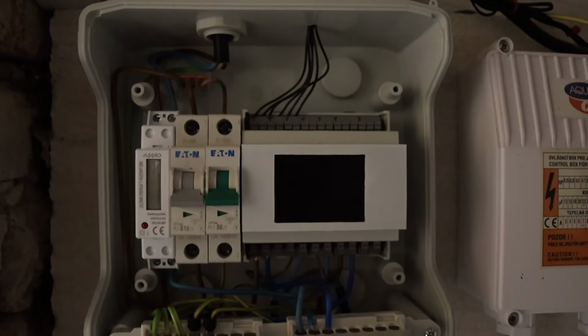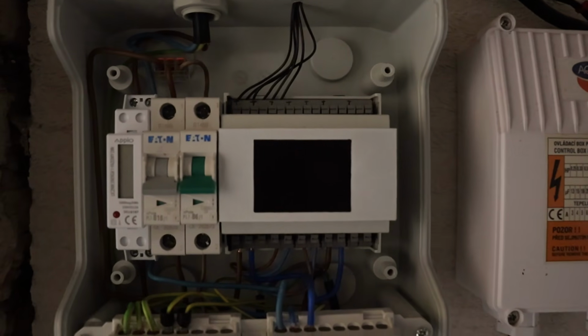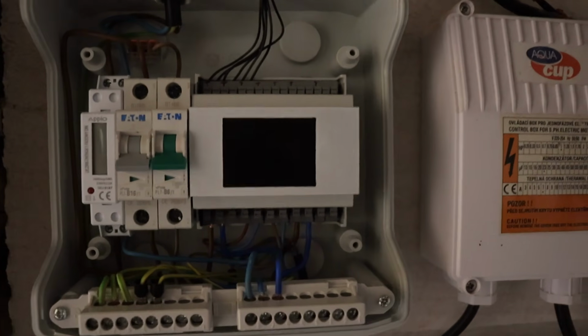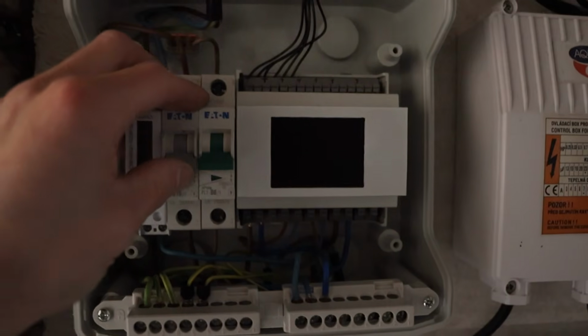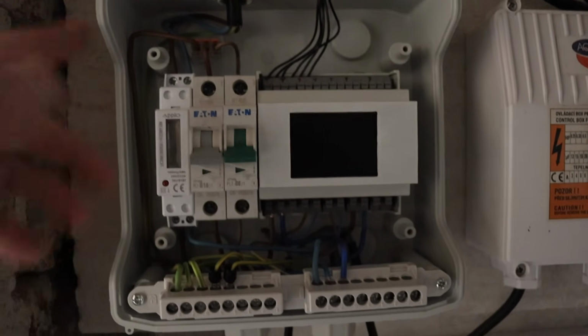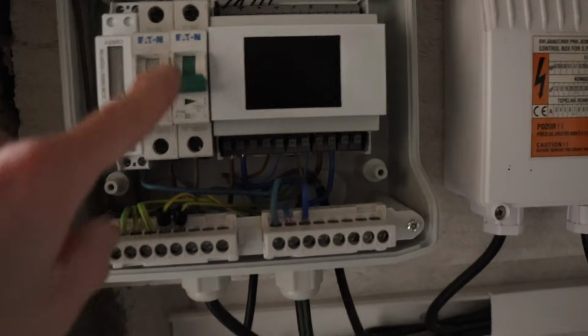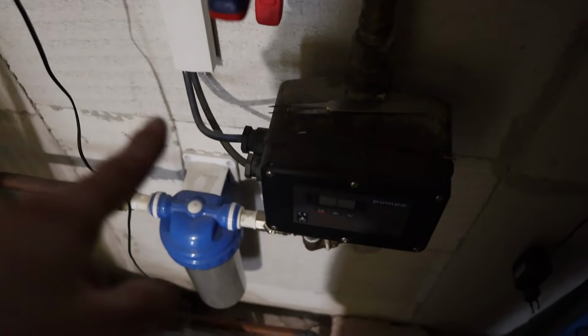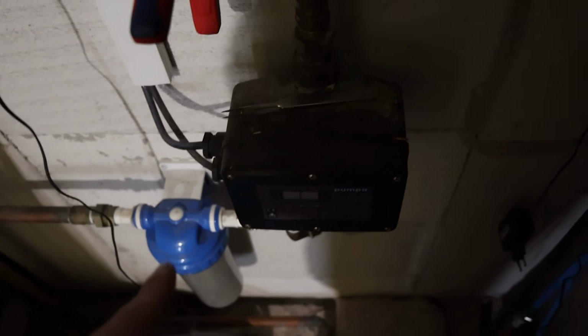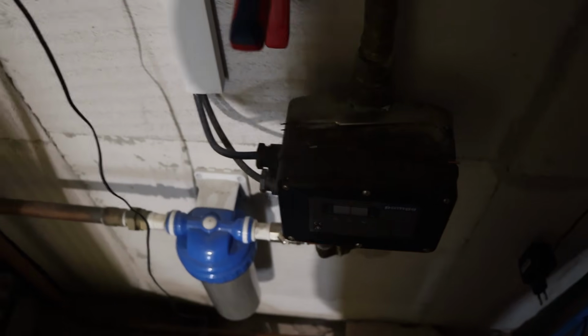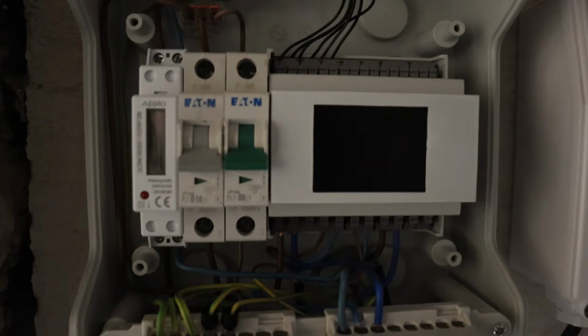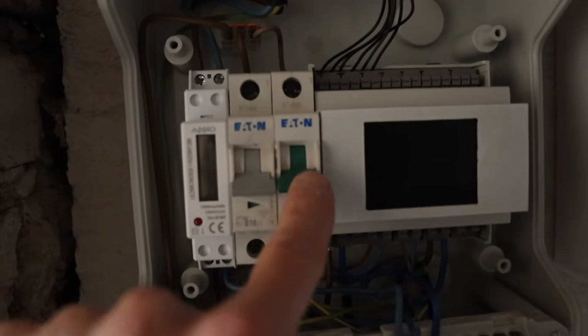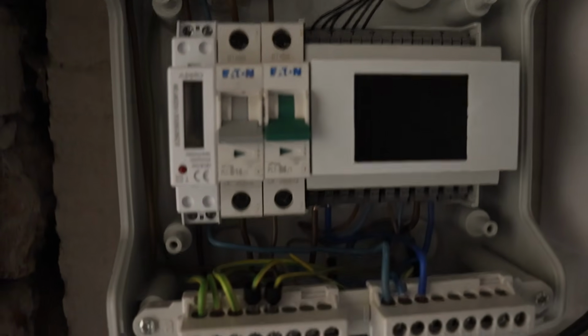Idea was nice, but reality is not as much. So first of all, I have realized that I need a 16 amp breaker here because of the master on-off switch. Then I need a 6 amp breaker here because this VFD, while it is connected via 1.5mm copper wire, the wire that goes to the pump is, I think, 0.75mm. I calculated it before. It is definitely good for 6 amps.